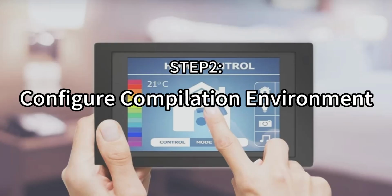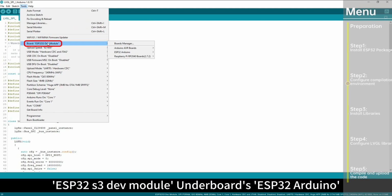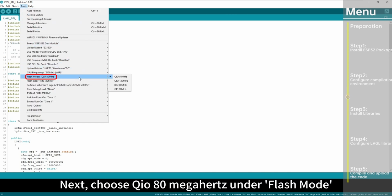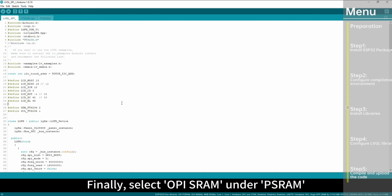Step 2. Configure compilation environment. First, click on Tools, then select ESP32S3 Dev Module under Boards ESP32 Arduino. Next, choose QIO 80 MHz under Flash mode. Finally, select OPI SRAM under PSRAM.